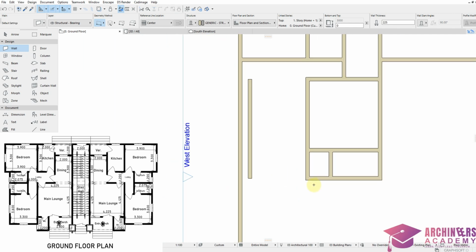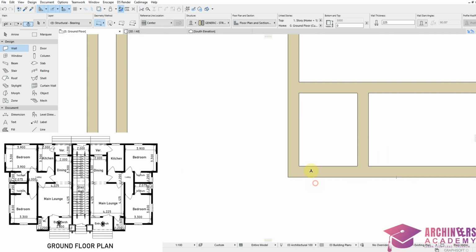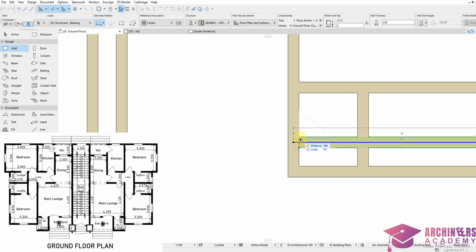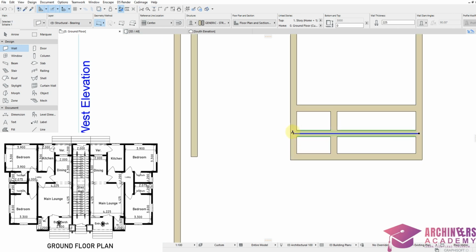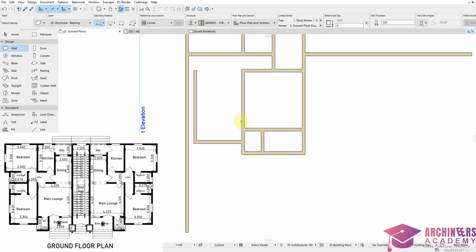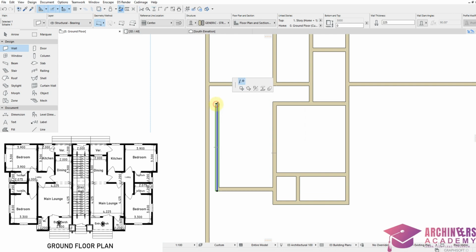If we observe this wall, the wall of the bedroom at this side ends where the window starts, where the window ends. So we're going to make the window 600 because it's a toilet window. The width is 600, so we'll add 600. Then add the thickness. So this is where the window ends. So this is the wall of the apartment. So I'm going to trim all this. Then this joins over to here. Now trim this also.